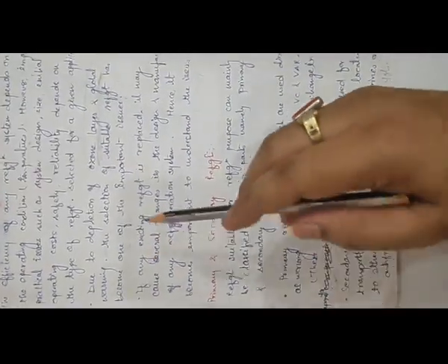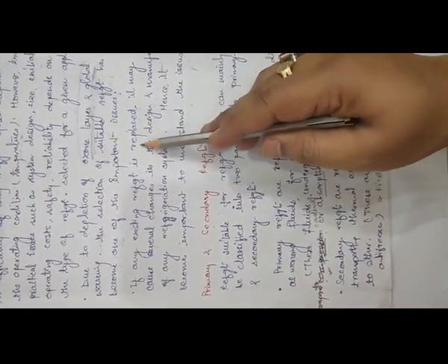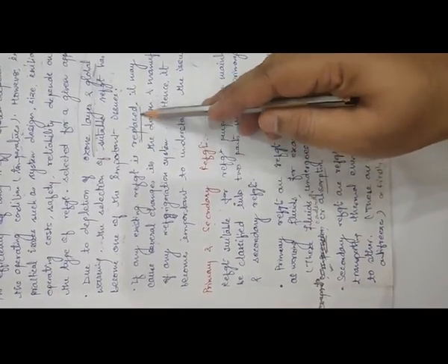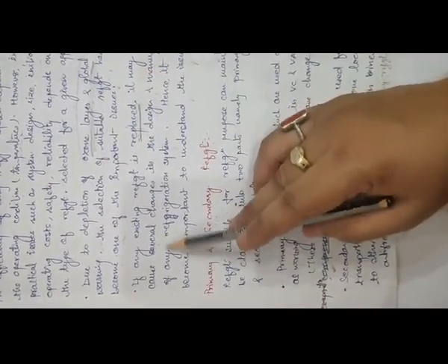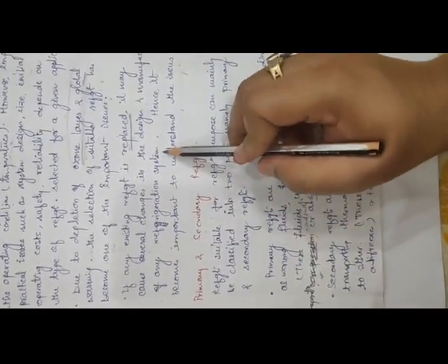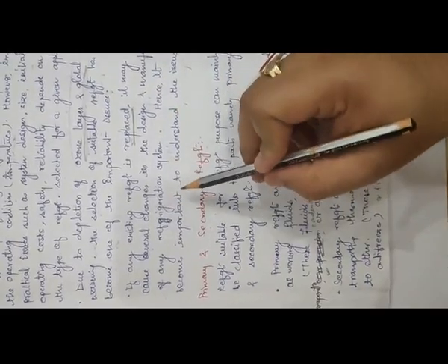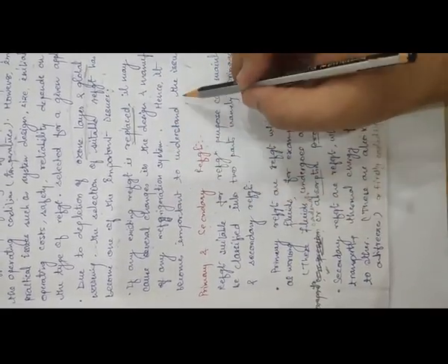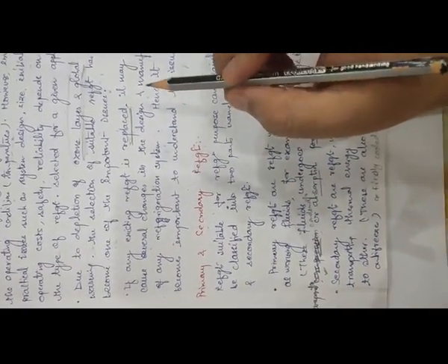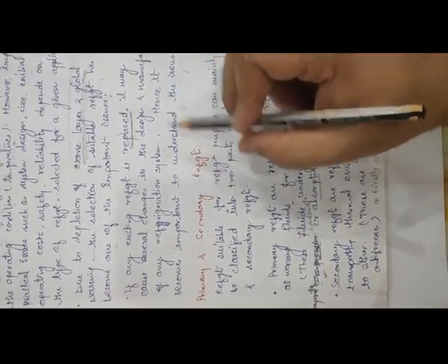Another point is, if there is any existing refrigerant and we are going to replace it, it may cause several changes such as in the design and the manufacturing of the refrigeration system. So we cannot go randomly for any refrigerant for any particular use. There should be some proper guideline for the selection of the refrigerant for a given application.